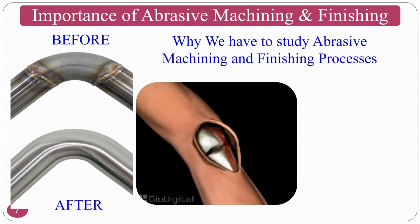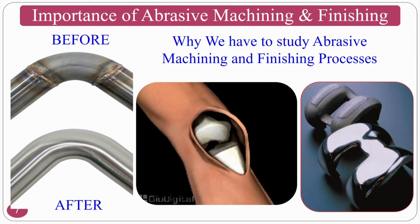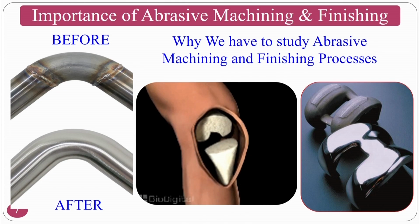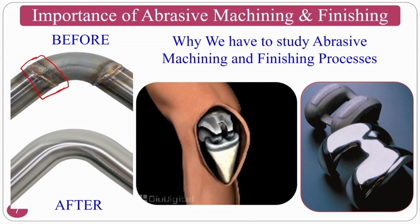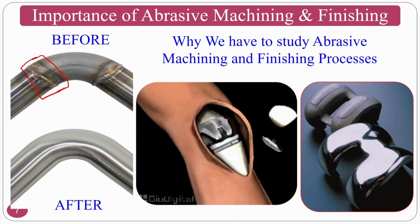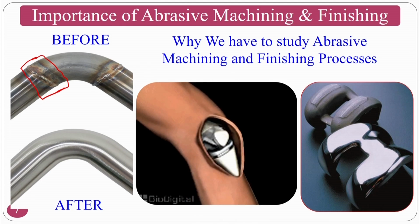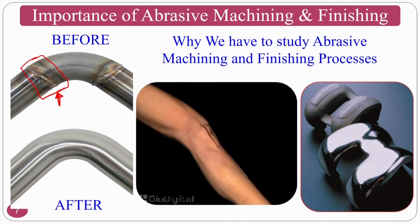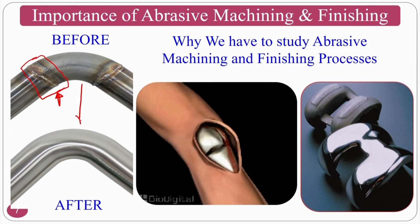And why we have to study abrasive machining and finishing processes, that you have to understand. Okay. Finishing is one of the final processes on a particular component. If you see here, this is a welding region, and if you are going to sell your product, assume that this is a gas pipeline or a petrol pipeline. What is going to happen is chemical reactions will take place at the metallurgical change locations. These are the metallurgical change locations. So, you have to do the polishing operation so that you can achieve from this to this.